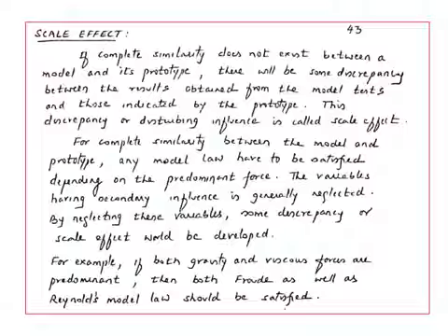So if complete similarity doesn't exist between the model and prototype, there will be some discrepancy between the results that are transferred from the model to the prototype, and this discrepancy is known as the scale effect. We have studied that if viscous force is predominating, then we have to use the Reynolds model, and if gravity force is predominating, we have to use the Froude model.